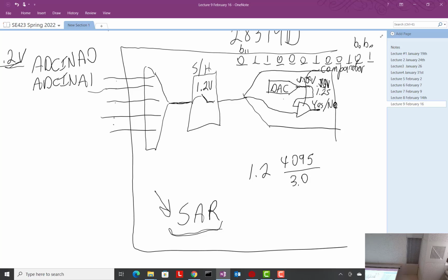Okay? And so when you're talking 100 nanoseconds, or something like that, you're only talking about 20 instructions in the processor. When you get into microseconds, then you're talking about hundreds of instructions. Because a microsecond is 1,000 nanoseconds, isn't it? And so divided by 5, that's 200 instructions. So when you start talking in microseconds, you're wasting a lot of time if you, for example, just wait for the ADC to be done.